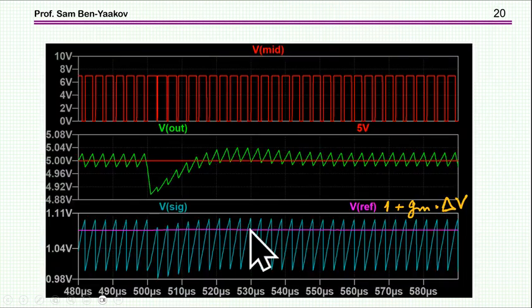And here is how it operates. I'm showing here the output voltage. There is again the 1 amp step load. You see that there is a drop, of course, due to the load, and there is a recovery. But as you can see, the average voltage of the output now is 5 volt, and once it's recovered, it's going back to 5 volt. Very, very neat.